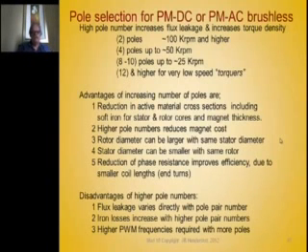So for PM and PM brushless, whether they're DC 6-step or AC driven, it's all based on speed. If the motor's going to go 100,000 RPM or higher, or frankly anything higher than 50,000 RPM, you have to use a 2-pole machine, because the frequencies are just too high for the inverter. This is true for induction motors too, or reluctance synchronous motors, high speed ones. You have to go to 2-pole.